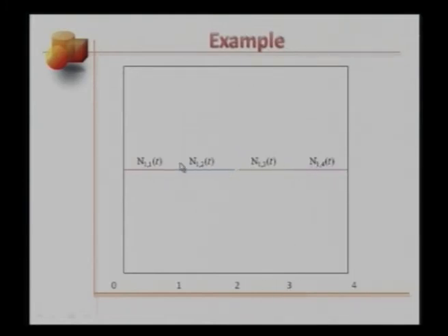All these normalized basis functions stand over a single respective knot span, as you would observe. Now this triangle corresponds to N22 of t. It's a linear interpolation between N11 and N12. It satisfies the definition of a spline. It is of order 2, meaning it is of degree 1. That would imply that it has to have position continuity throughout. So there would be 3 junction points, junction 1, 2, and 3.